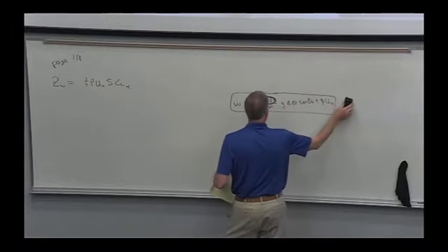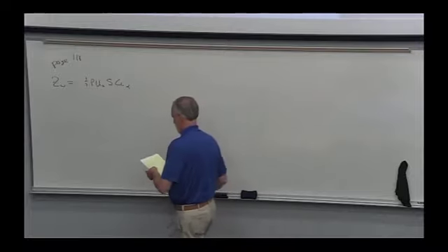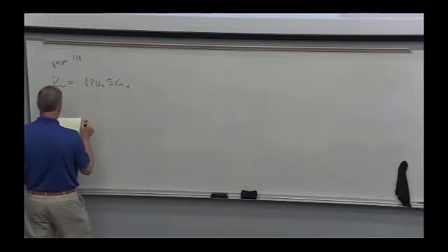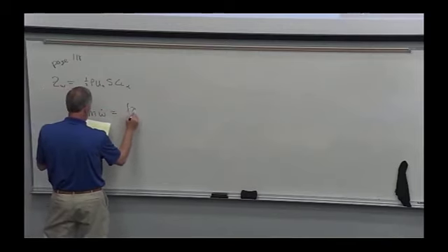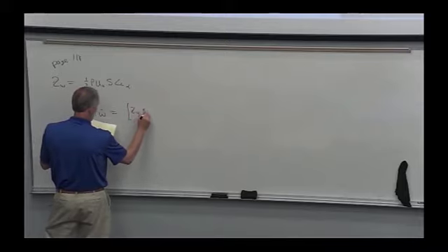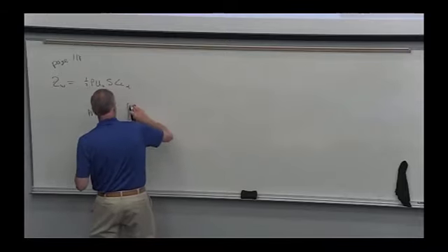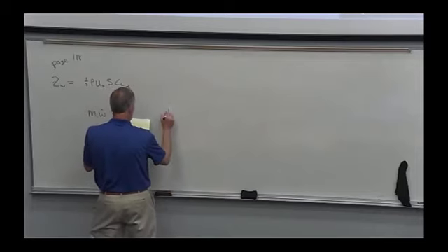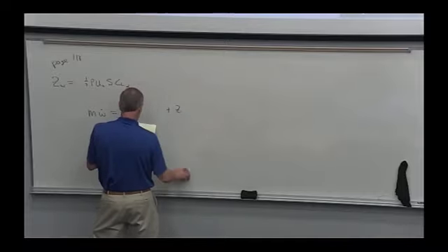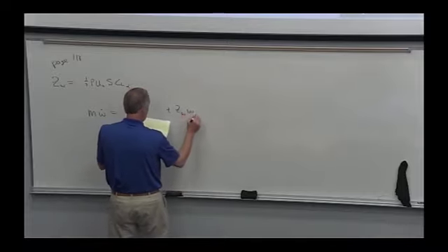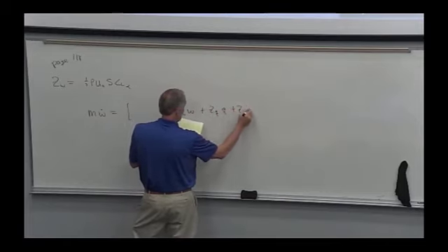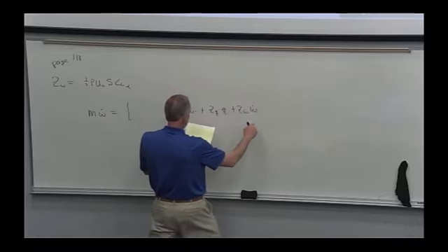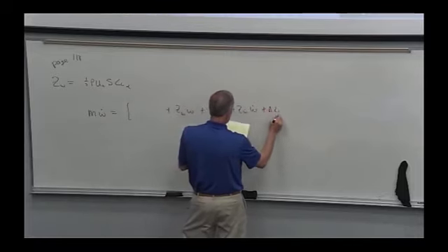So I'm substituting in for that. Leave a space here because I'm going to add something in. I'll get it right. This is ZW times W plus ZQ times Q plus ZW dot times W dot. So that's delta Z. Here's the control term that has the elevator in it.